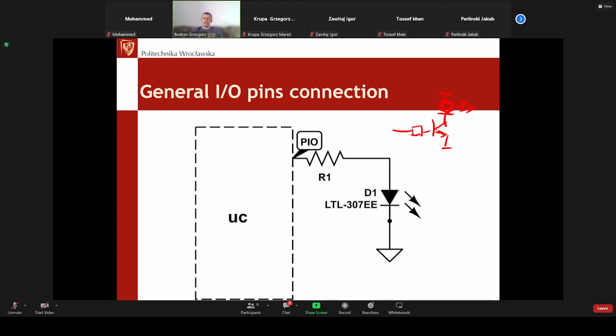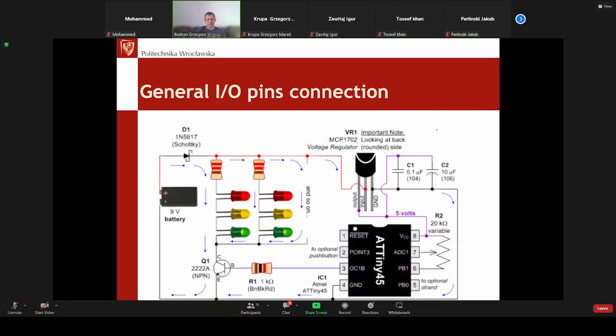Although, a driver is still needed if the LED is to be supplied with a current value exceeding the capabilities of the I/O port of the microcontroller. So, for example, if you want to make a very strong LED with half an amp or an amp, then you should use this kind of circuit. I thought about bipolar and CMOS, but there is no difference here.